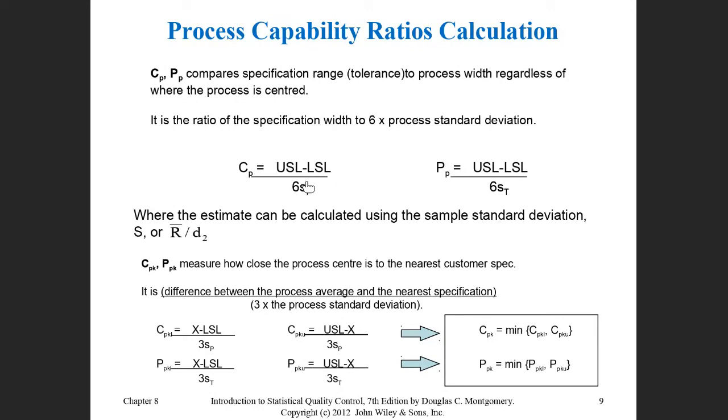In the process capability ratio, the CP and the CPK, the standard deviation is estimated, whereas the standard deviation for the process performance ratio is for the overall data. So you don't have a sample, you have the whole population. That's why it is rarely used, because in most cases we deal with samples, and in this case the CP will be the one used because it uses the estimated standard deviation.